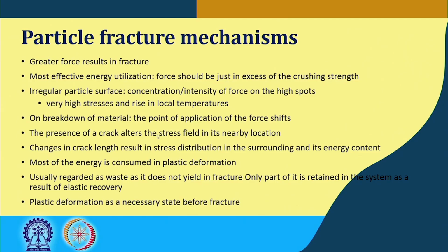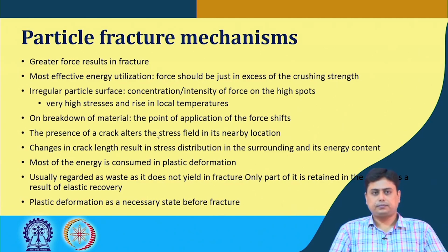Once it breaks down, this application of force shifts, and the presence of any crack results in stress distribution in the particle. This change in crack length as it propagates results in stress distribution and changes the energy content in the solids. Most of the energy supplied for size reduction is consumed in affecting the particle's plastic deformation, and this plastic deformation is a necessary step before the fracture occurs.